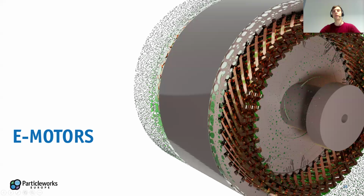Similarly, we did something in the e-motor cooling sector. We have new designs for automotive electric motors that require oil jets, direct oil cooling, instead of indirect water jacket cooling, because here we are looking at e-motors that are much denser in terms of power density.